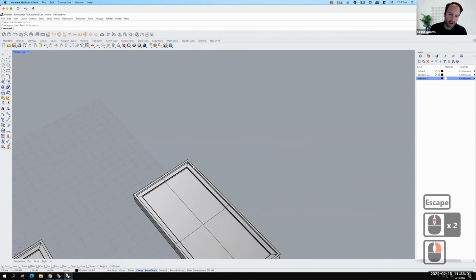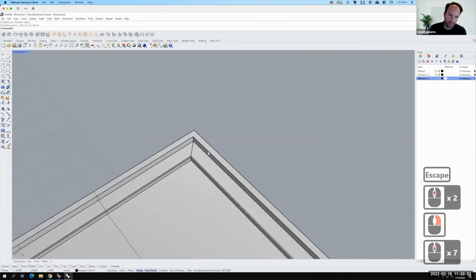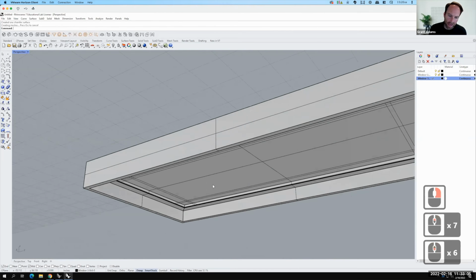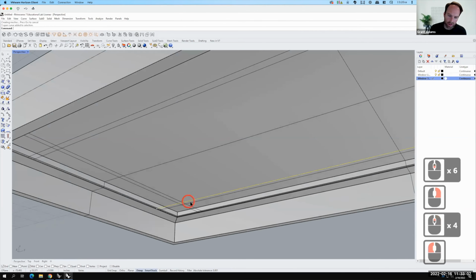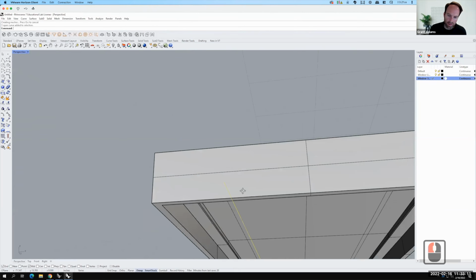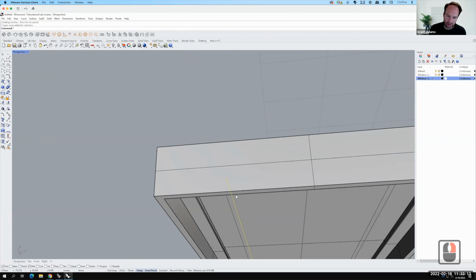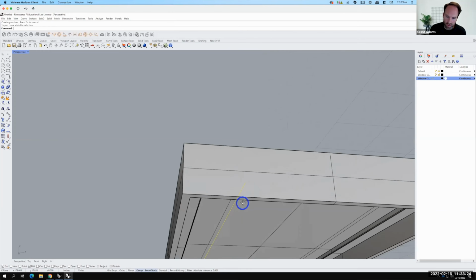So I've managed to do the chamfer on this. Maybe I want to add some mullions on the window. So maybe it's something like this. Now, maybe I don't want the profile of this mullion to be rectilinear. Maybe I want it to be curving. So I could establish the profile and then do a sweep on that profile to actually create the shape.